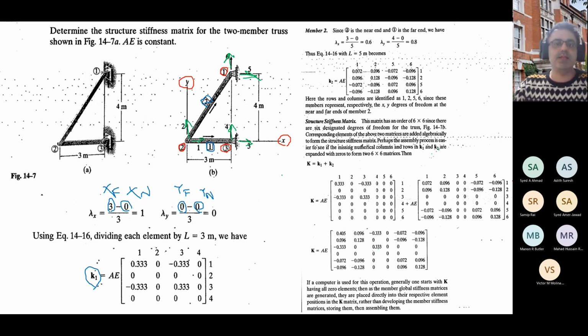So we have all this together. Don't forget, we define the coordinate system, we number the nodes, we number the elements, we number the degrees of freedom. If you do those, it's very simple to assemble these kinds of matrices.